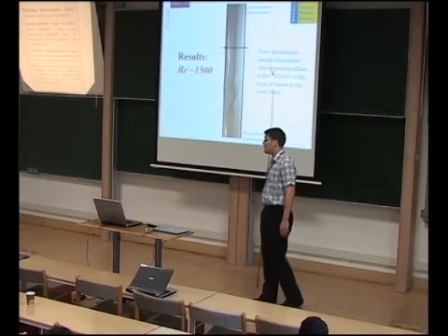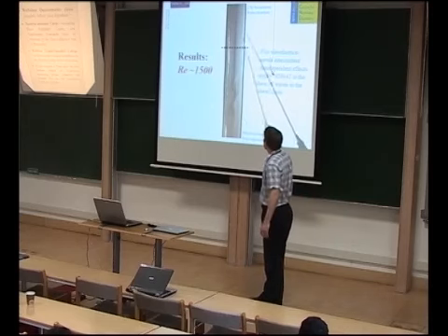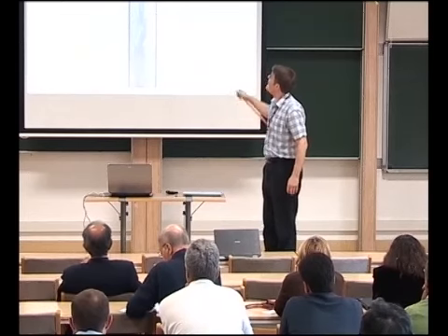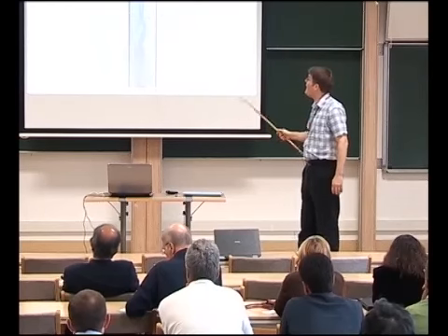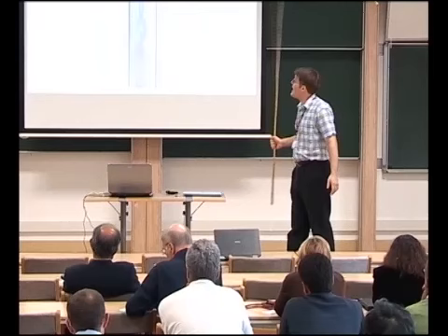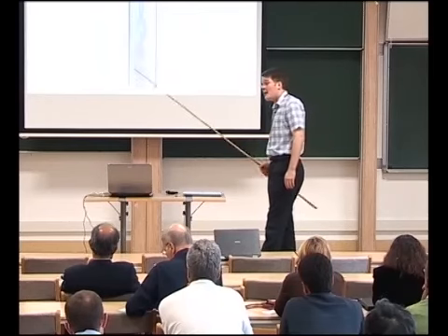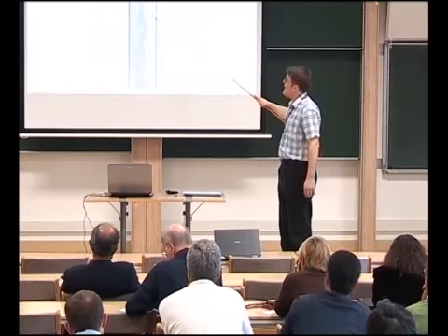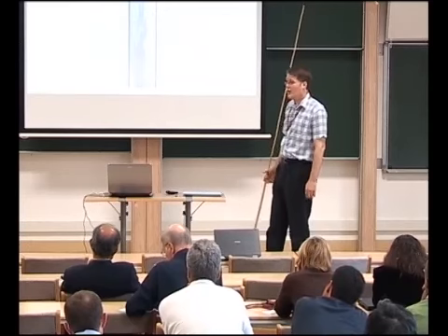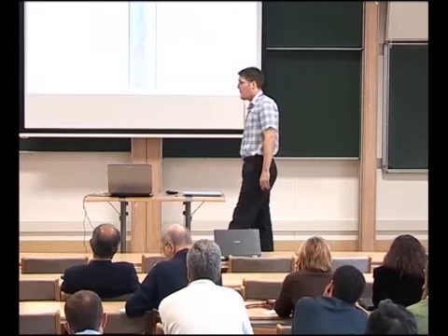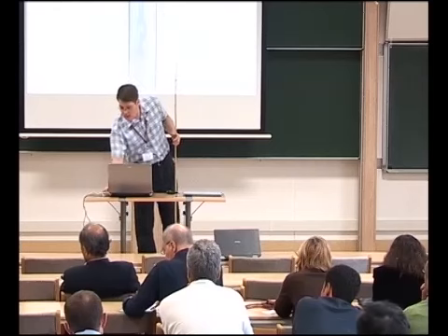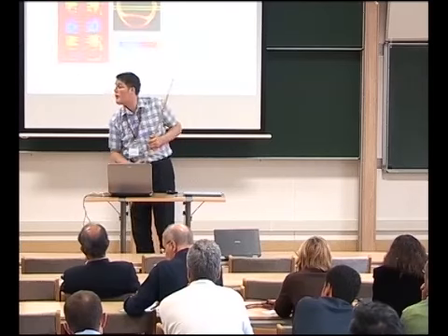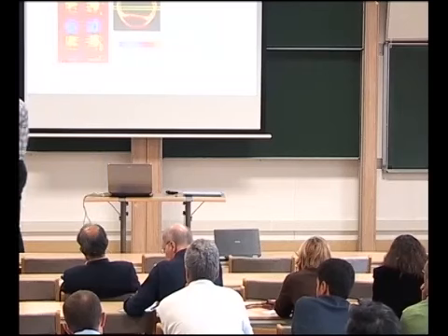Then we found that as we removed more and more mechanical noise from the system, we clamped it to the ceiling, this disappeared and revealed the symmetry breaking bifurcation. What happens is it starts at this point here, always the same point, you get this wave, and it sustains for maybe 5 or 10 seconds, and then disappears. When it disappears, it may detach and move downstream one diameter or something, but it goes pretty quick.